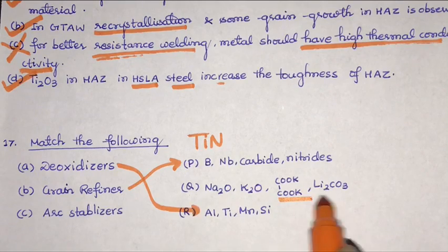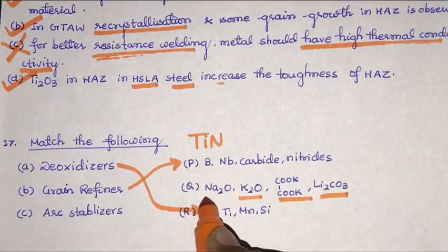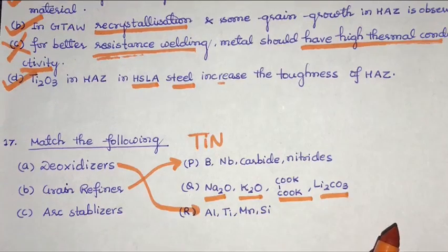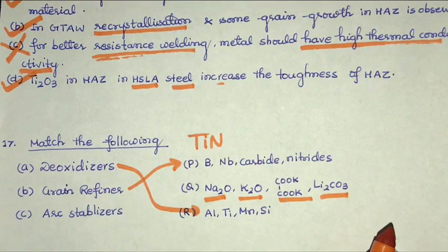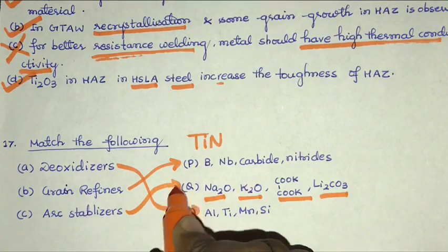Potassium oxalate, lithium carbonate, potassium oxide and sodium oxide can easily decompose into ions and increase the electrical conductivity of the arc. So it helps the arc to conduct electric current more smoothly. So it will match with this.